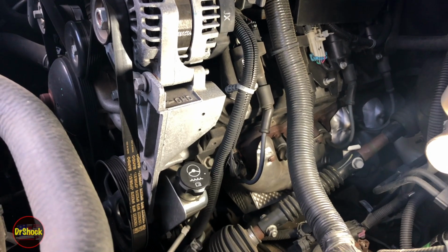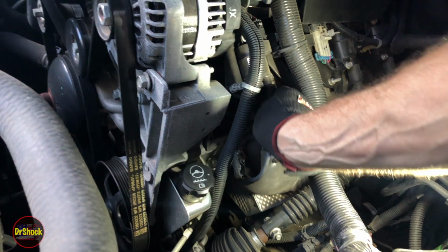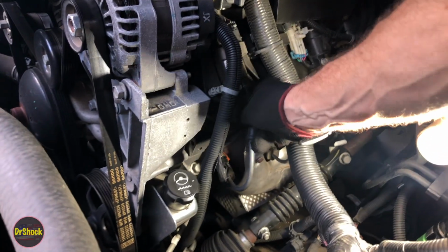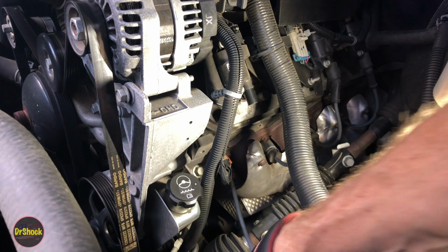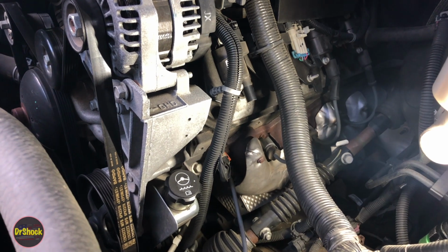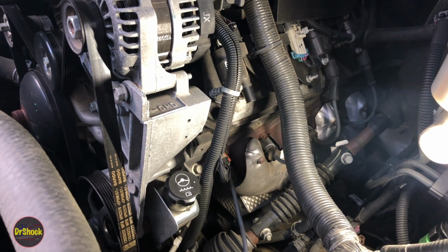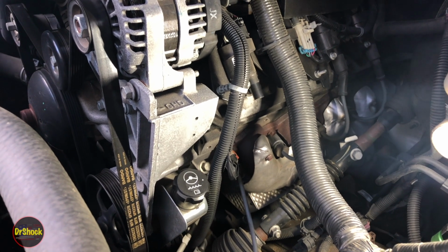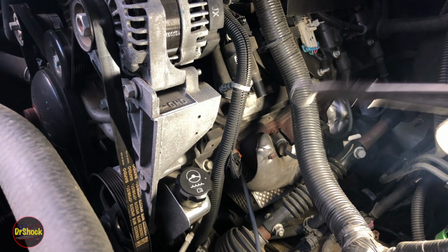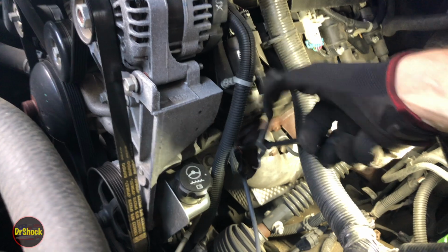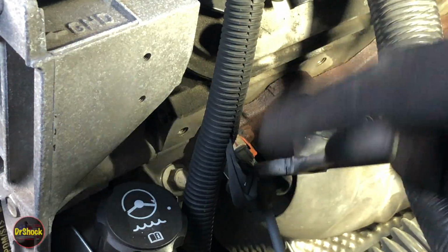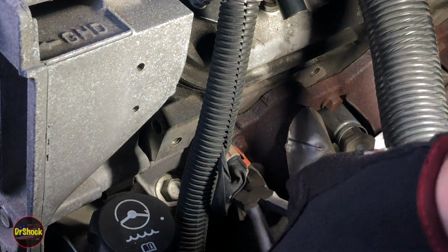in some sense, debugging one of these P0300s can be manufacturer and engine specific. So we've got a 5.3 liter RPO LC9 engine. That's an engine with active fuel management, or AFM. And so we know that this is an oil burner. That's just how it is. 2013 model, this many years down the road, that's just where things are at. So we can suspect that that could be causing a problem, right? Because you can get fouling of the plugs, for example.